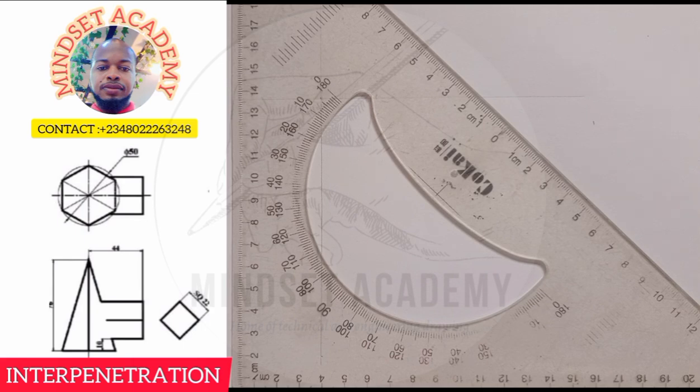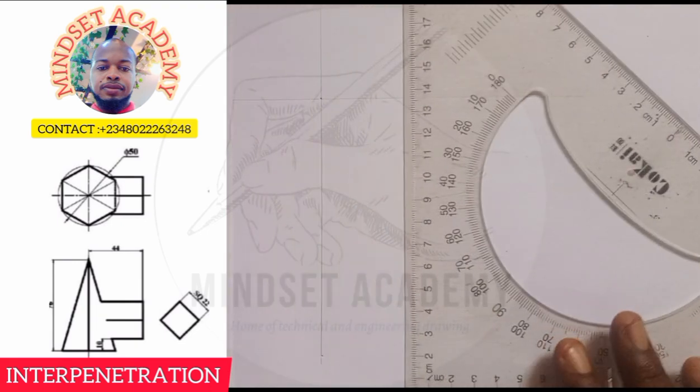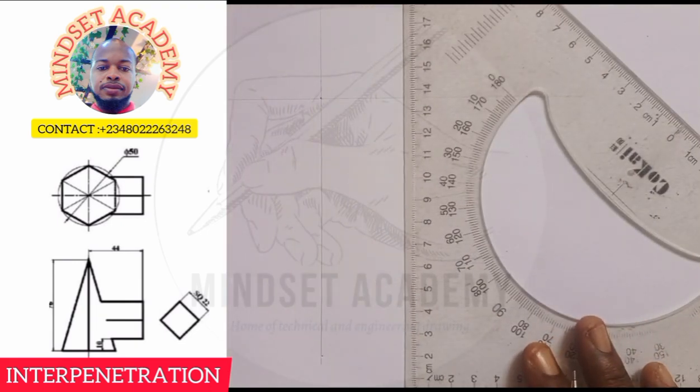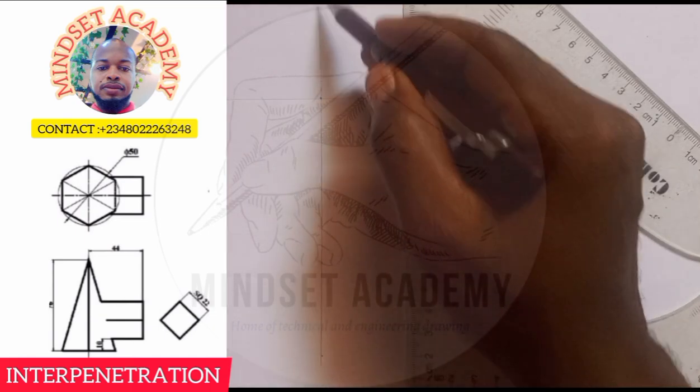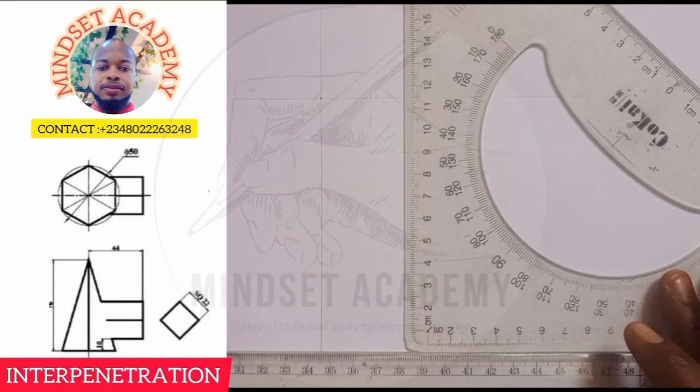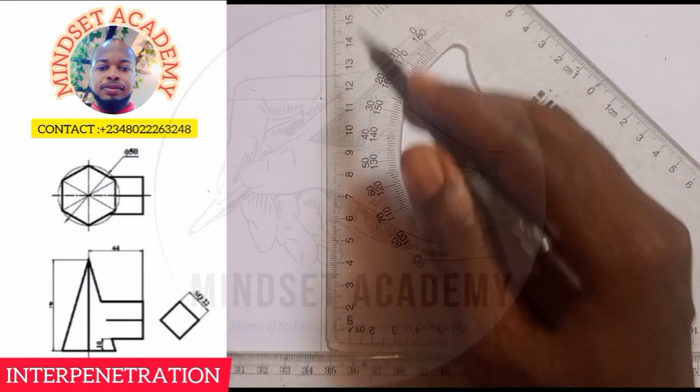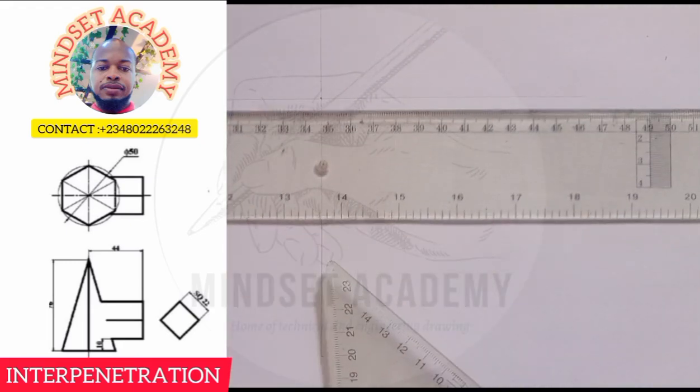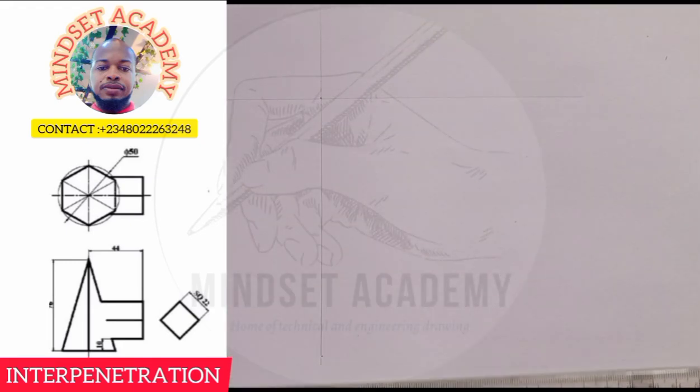From this you can see we are given the plan and the front elevation. This is the plan and this is the front elevation. So what we are going to do is draw out what we are given. Let's start. The first thing you do is draw your vertical and horizontal lines, just like I did here. You draw your vertical line, placing your set square on your T-square, and using your T-square to draw your horizontal line.